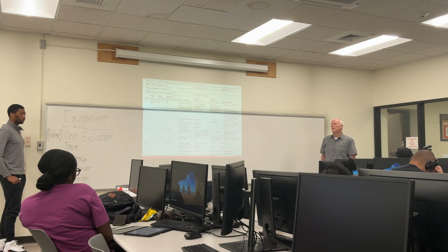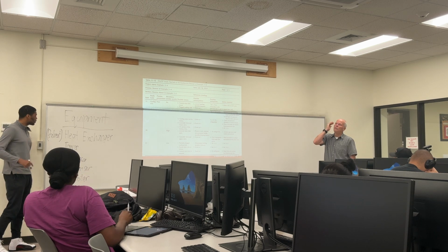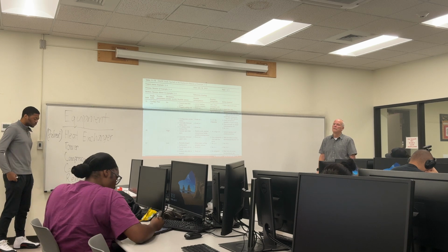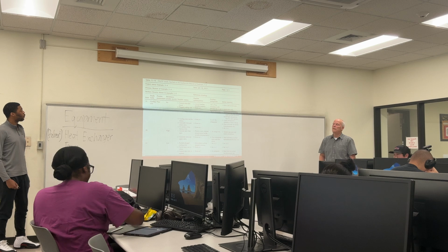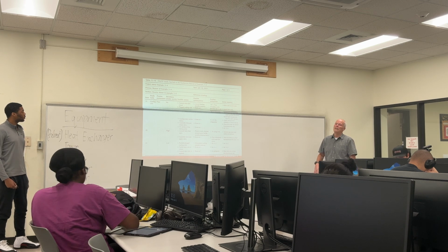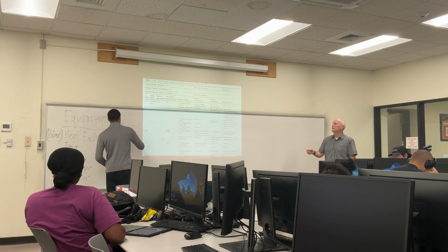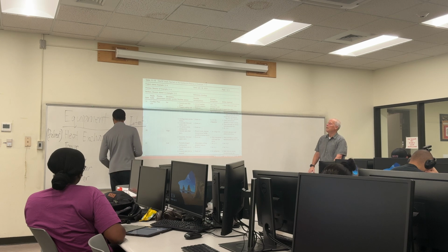I'm not sure we ever talked about that. How do I, you guess, control it? Increase, decrease power depending on what the outlet pressure is and if it's meeting spec. Yeah, you really can't control the pressure by looking at the outlet pressure, or the pressure differential. Usually what they do is they base it on the inlet pressure. So the suction pressure is responsive to the turbine speed. So you'll adjust the speed of the compressor based on the inlet pressure.